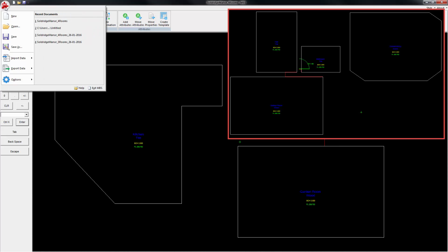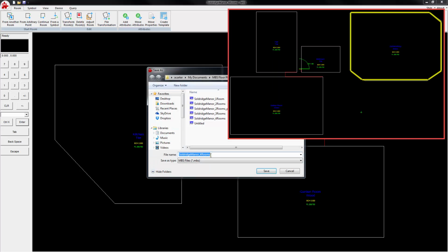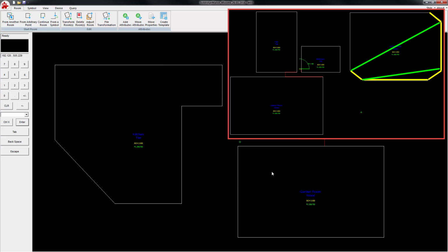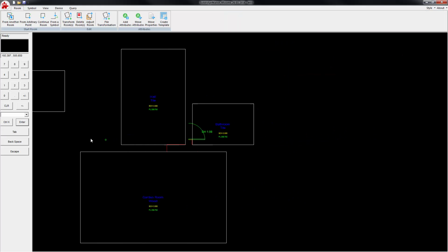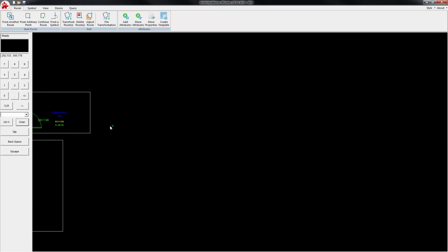We are going to compute an irregular shaped room, the conservatory. It has several walls, one after another, that are not at right angles, so cross braces are required for the computation, which needs to be conducted in several stages. The room will be started from an arbitrary point. Pan to move to a clear space and use the cursor to select an arbitrary point to start the room, clear of the room surveyed so far.